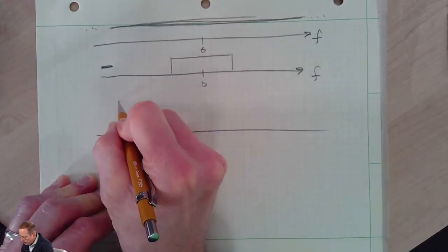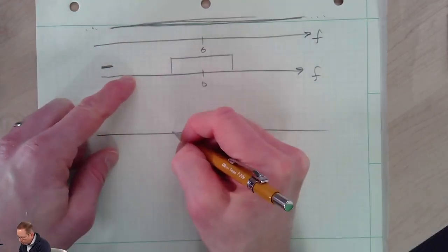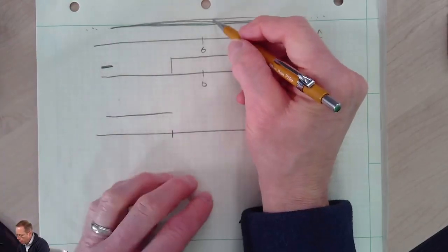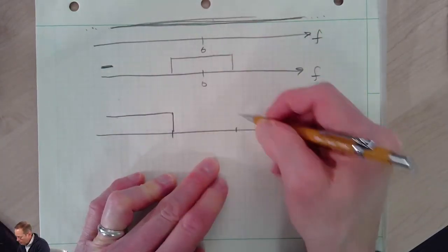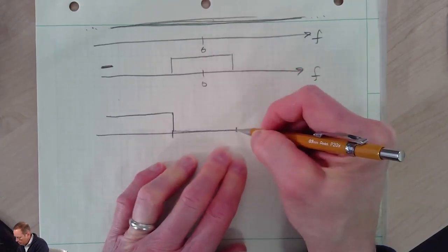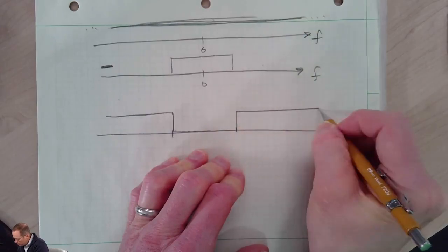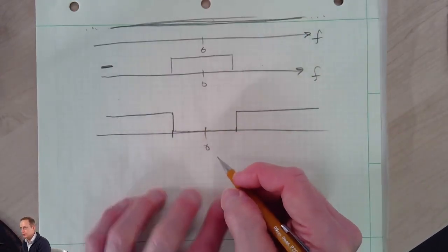Can you see that, when I do that subtraction, I will have 1 minus 0, gives me 1 up to this frequency, and then I have 1 take away 1, then up to this frequency that's going to be 0, and then over here I have 1 take away 0. And so now you see that we have a high-pass filter.